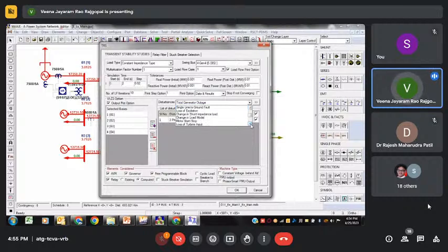Loss of excitation, change in shunt impedance, change in load model, motor. If you have a motor, we don't have a separate study for motor starting, so that is a part of this stability. Then you have the loss of turbine input. These are the different disturbances that can be simulated. Even the single pole opening, two pole opening, then the wind farm outage. This is for wind and solar park outage.